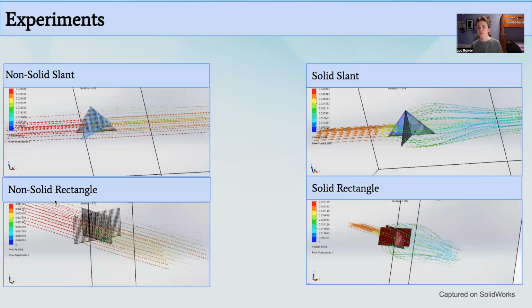This study originally planned to make use of a lattice-Boltzmann simulation coded in Python to model fluid flow. However, time constraints proved to render this infeasible. Instead, I used SOLIDWORKS as an apparatus for modeling fluid flow. Given the depth and location of the Chondrocladia lyra, I was able to obtain information for the velocity distribution, temperature, and pressure of its natural habitat, which is crucial for modeling fluid flow. In terms of velocity distribution, the velocity ranges from 0 centimeters per second to 12 centimeters per second. It has an ambient temperature of around 1 degree Celsius, and the pressure is around 337 atmospheres.